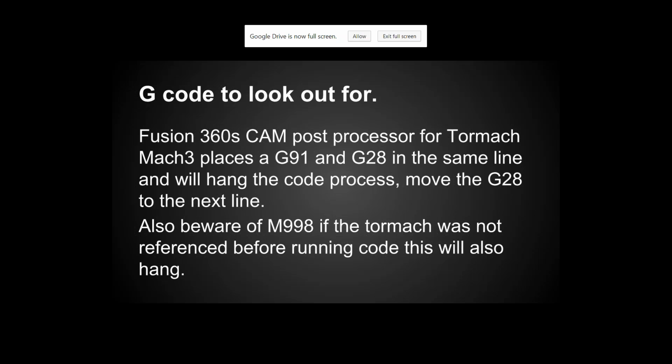Do you want to use taper pins to locate things, or typically screws, or just shoulder bolts? No, if you get a shoulder bolt, it will have the diameter, which, unless you're specifying like 4.1 inches or something, you will have a shoulder bolt the size of whatever pivot bolt you're going to be running. Like in the part there, we had 10 millimeter holes. You can get 10 millimeter shoulder bolts. You might actually even have a problem getting the shoulder bolt into the hole. There'll be an interference fit. You might have to lightly sand the shoulder bolt to make it fit. Or you can machine a pin into the plate and then just use a work holding clamp to hold the part down.